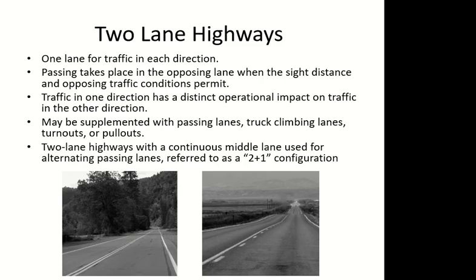These two-lane highways can have temporary lanes in special cases. For example, they may have passing lanes. There can be portions of the highway where overtaking from the other direction will be more dangerous because there is no sight distance. So you may create a temporary third lane to let the passing happen for that segment. This is called a passing lane.